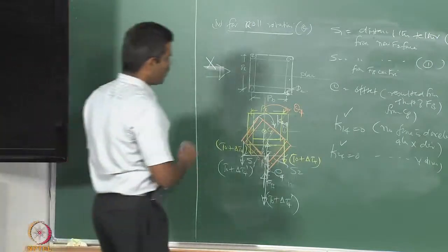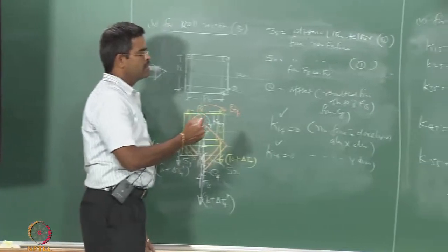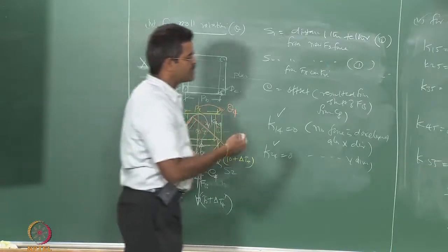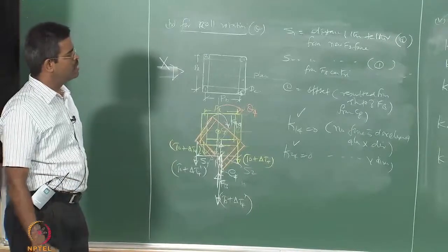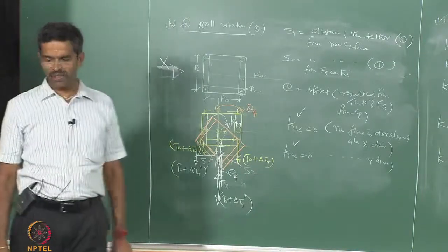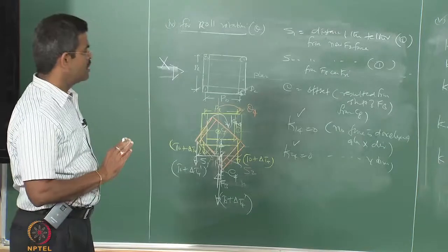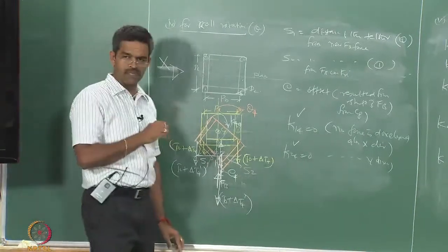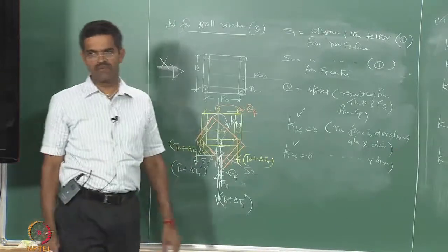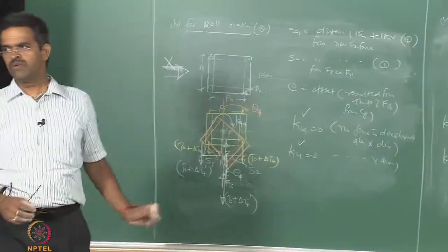So any doubt here? We have derived the members or elements of the stiffness matrix step by step from first principles by giving unit displacement in the respective degree of freedom, and we got the forces in the respective degrees, keeping all of the other degrees constrained. Then there are some very special characteristics of the stiffness matrix members, which I will discuss in the next lecture, which is very important. Any doubt?